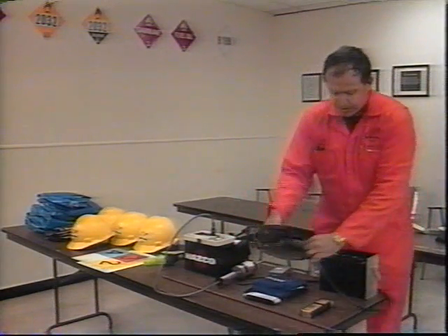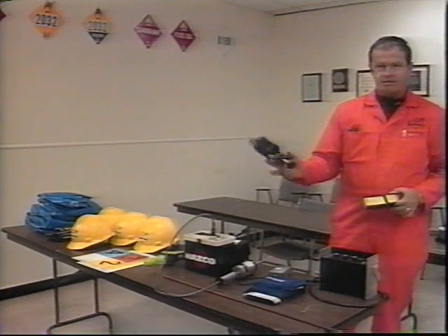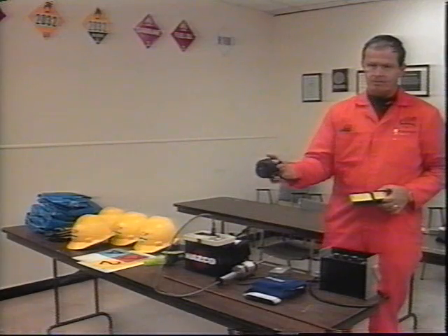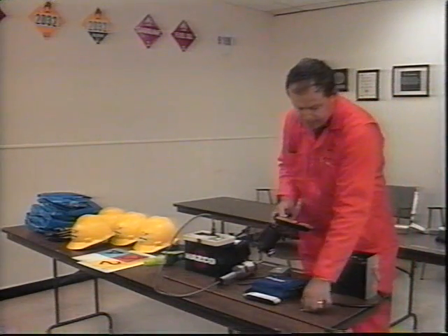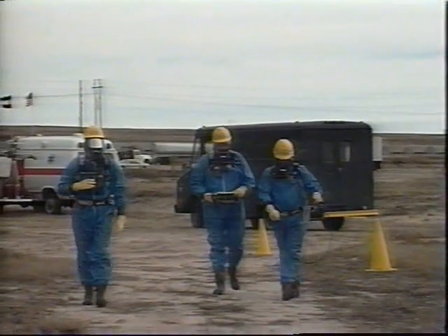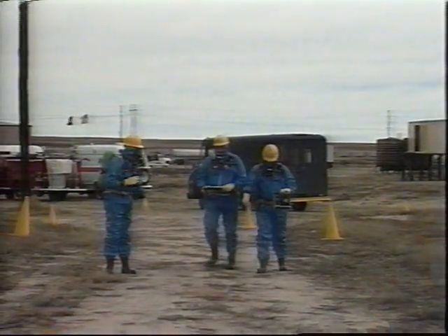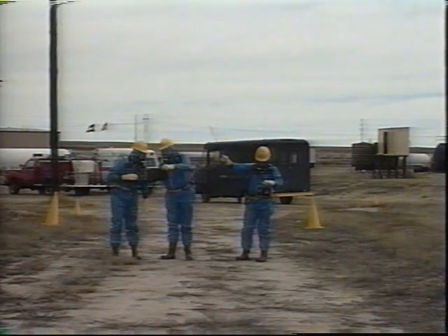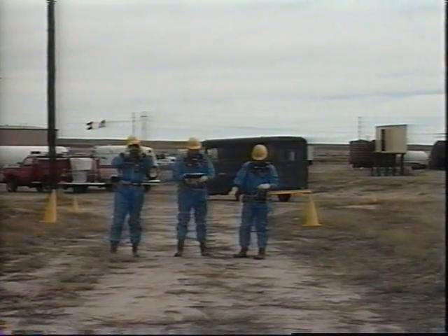Unfortunately, single workers cannot carry multiple sampling media because of the added strain and because it's not usually possible to draw air through the different sampling media using a single portable battery-operated pump. Consequently, several days may be required to measure the exposure of a specific individual using each of the media. Alternatively, if workers are in teams, a different monitoring device can be assigned to each team member.